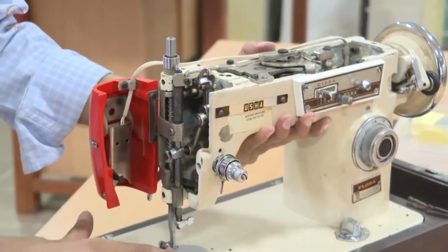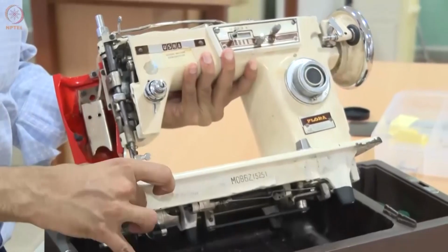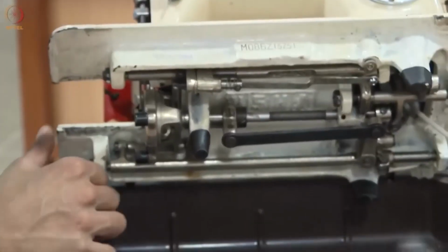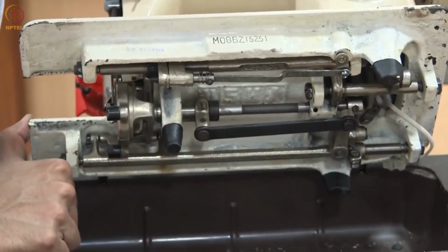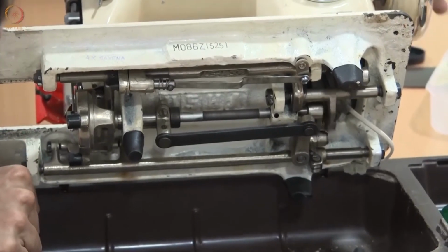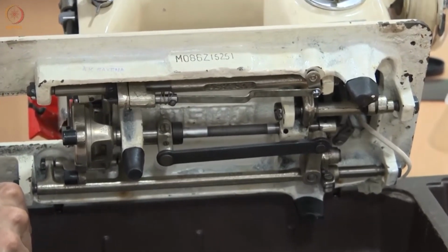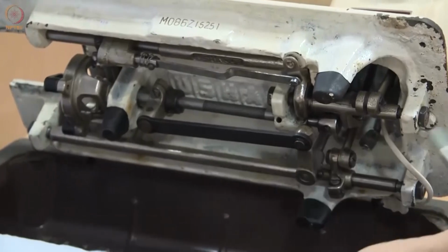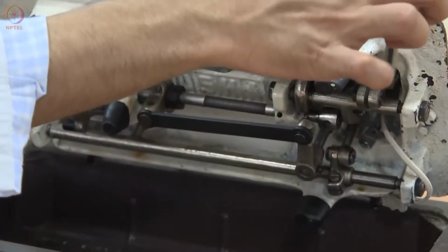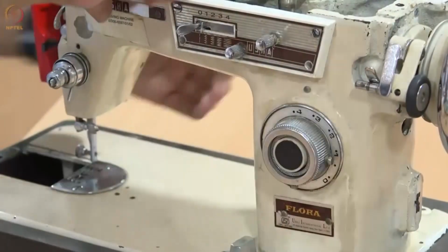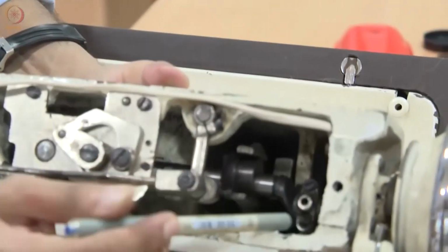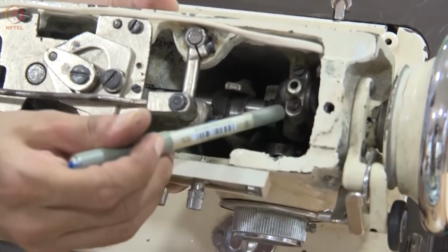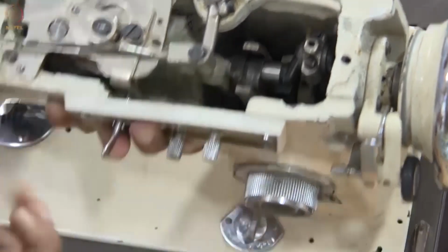Now let us look at the bottom part of the mechanism. This is where all the much more interesting mechanisms lie, right? Remember the very first mechanism I showed you, there is a crank there. In this case, it's not a crank slider, it's a crank rocker. So that connecting rod that you saw, it is this connecting rod. So this basically connects here. This is the connecting rod that I'm pointing out.